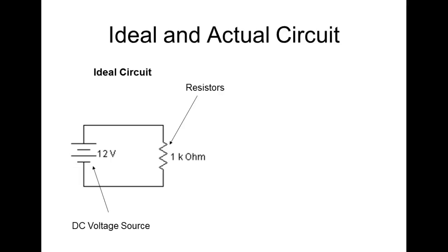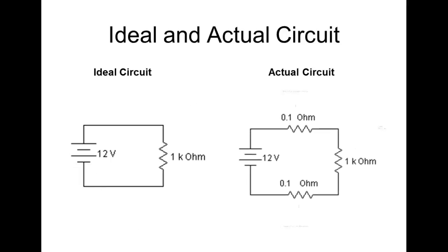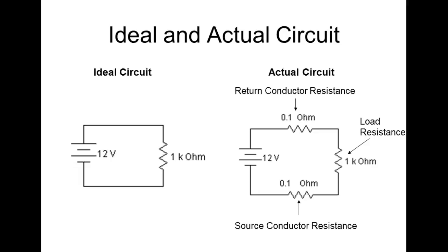So voltage drop. Everybody okay with voltage drop? We looked at an ideal circuit, and then we looked at a real circuit in DC. So everything that we deal with has an R component, right? You understand that? And if we push current through R, what do we get? We get a voltage drop. So it means all your conductors are going to drop a small amount of voltage, right? Now, if we choose the right size for the right length, this voltage drop is so small, it's really negligible.